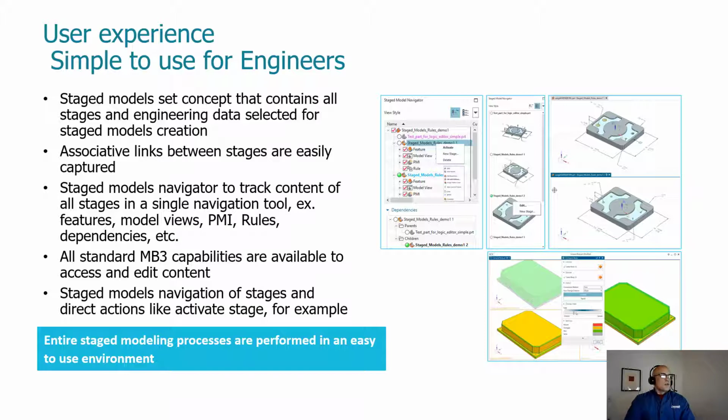So as we created the different modeling stages, there is an associative link between those different stages. So if the parent was to change in some way, that's going to propagate all the way through those 5 additional stages. So you're going to be able to define, create, and manage those stages and focus on improving the efficiency of your parts. So you're leveraging NX, the PMI information, if you do have that license, and it's going to be able to drive rapid authoring for downstream manufacturing information on that particular stage model that you have.